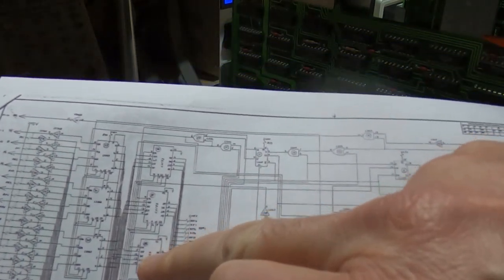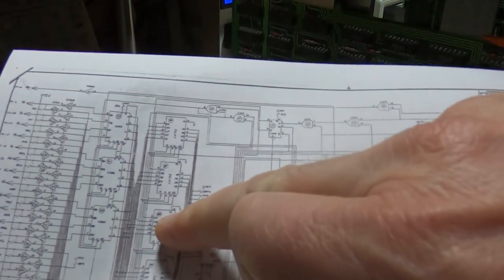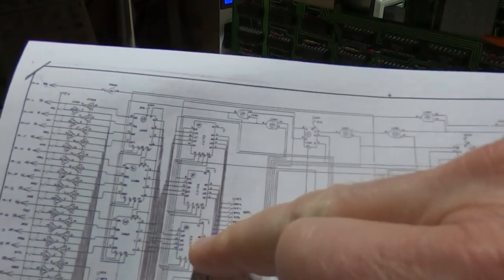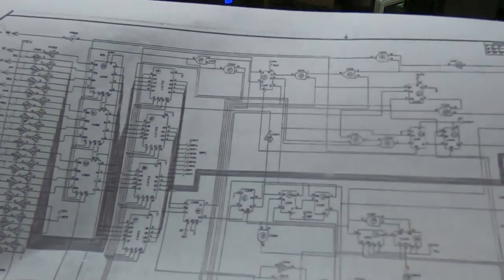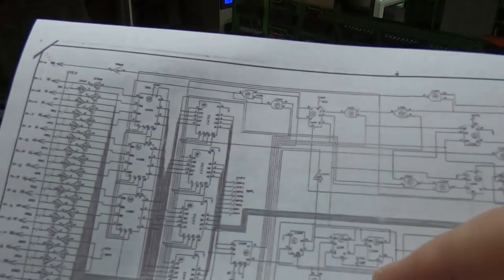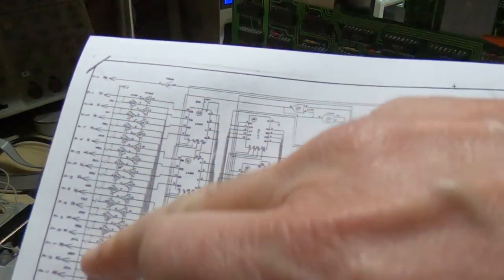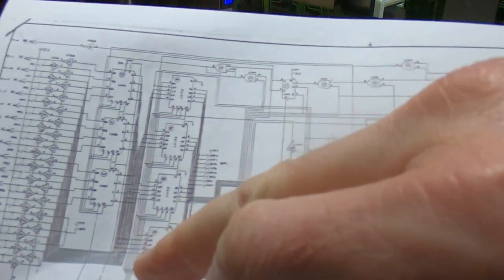So what I'm going to do is the same trick I tried in a previous video of piggybacking another IC on here. Now you've got to be careful doing this. I'm only doing it here because the only things that are connected to these are devices I have replacements for. I would not suggest trying this technique on something like this, where it's connected directly to the hybrid module. You could damage the hybrid module.